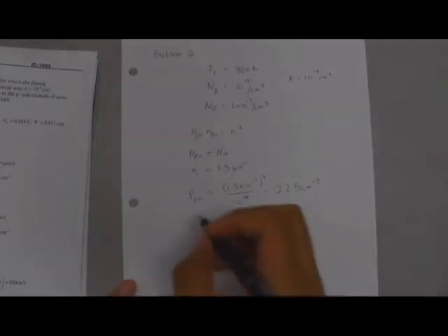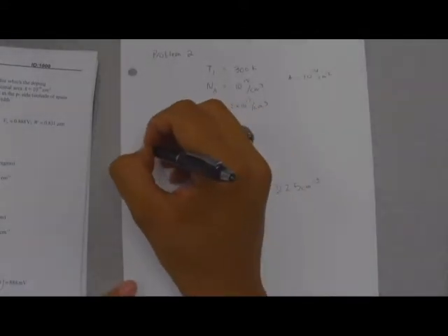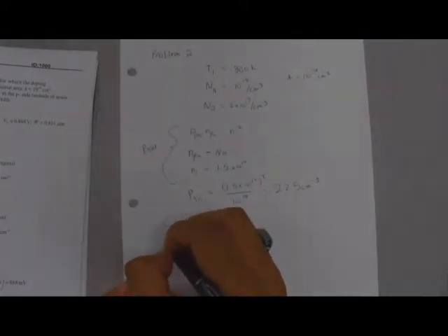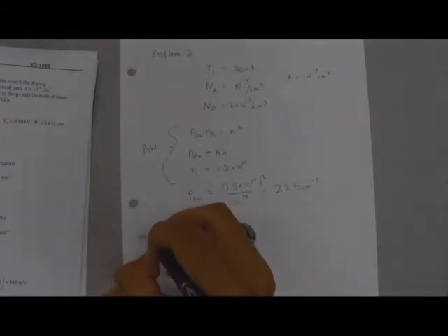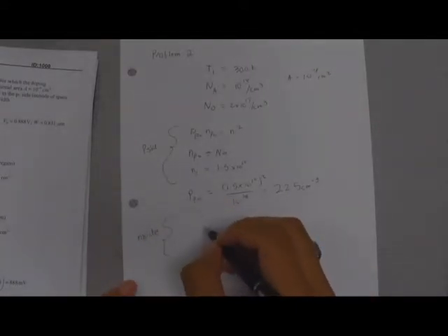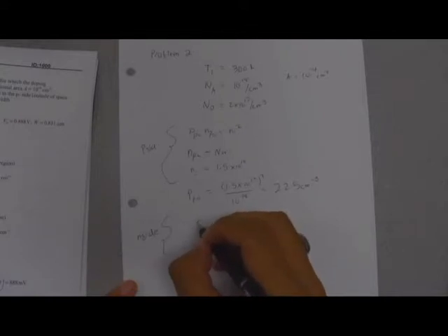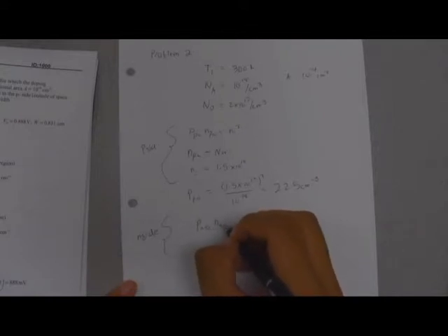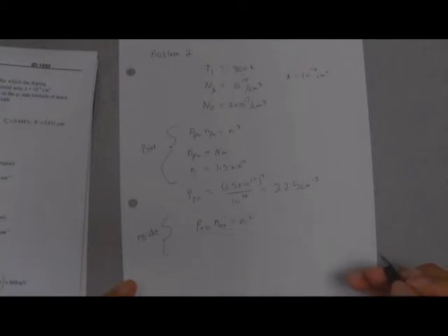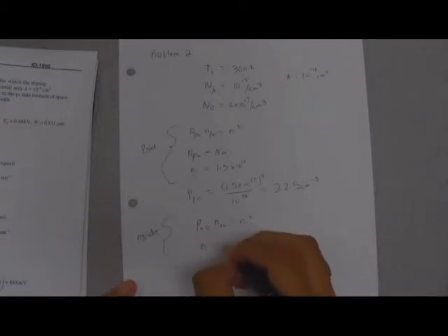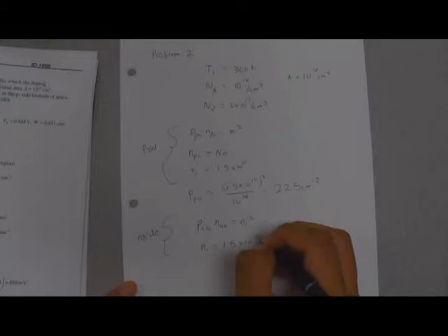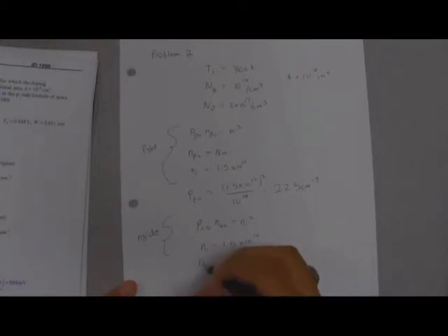We're going to do a similar step for the n side. So this was all of the p side. So we're going to be using this formula. Again, Ni is going to equal 1.5 times 10 to the 10. n n0 is going to be approximately equal to Nd.